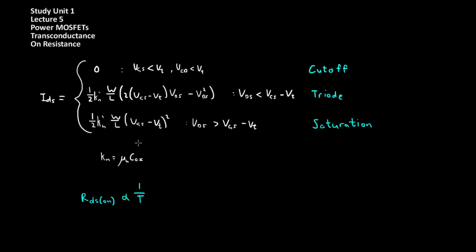An important distinction between a MOSFET and a BJT is that in a MOSFET, second breakdown cannot occur. This is because the RDS, or on resistance, of the transistor is proportional to temperature, which means that as the current increases, the temperature will increase. What this means is that the on resistance will also increase, thus reducing the current. In other words, if any hotspots form in the silicon, they are automatically diverted away, reducing current and reducing temperature.